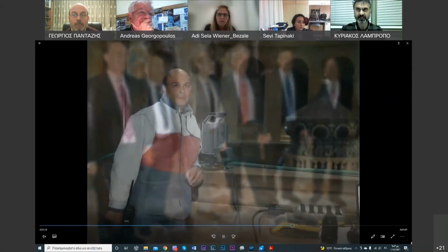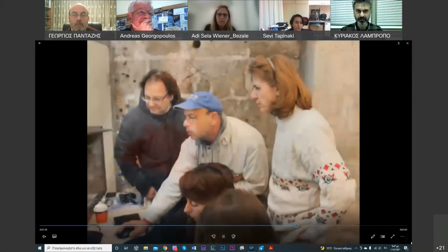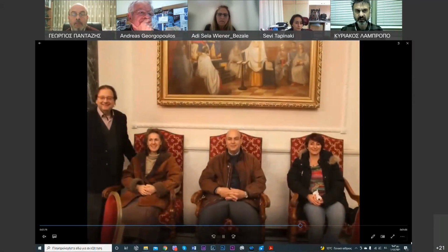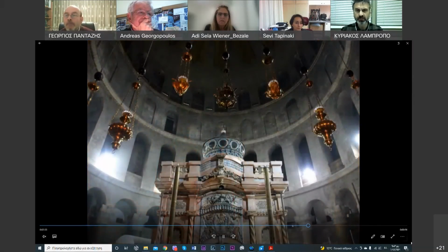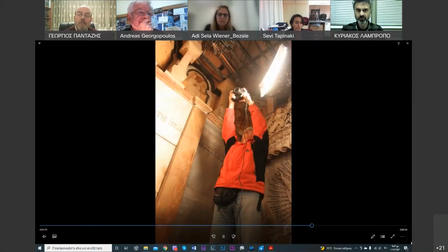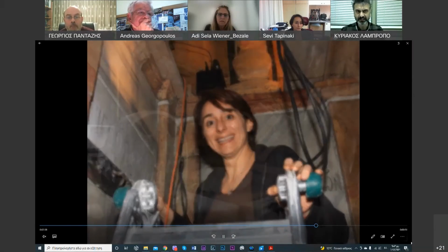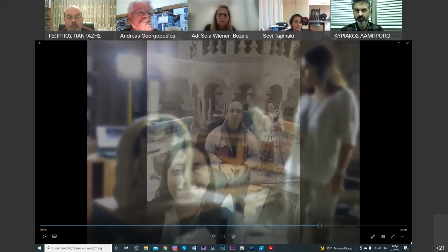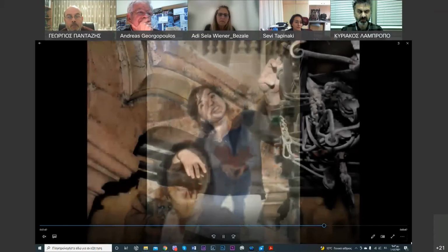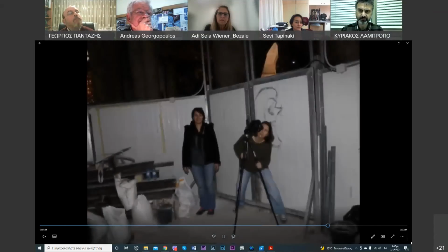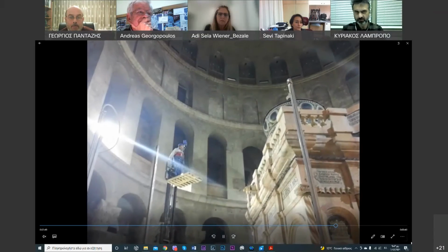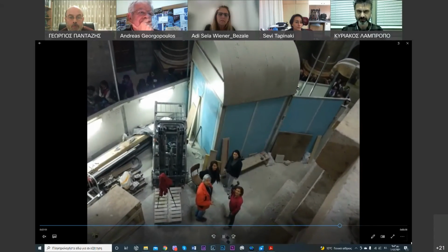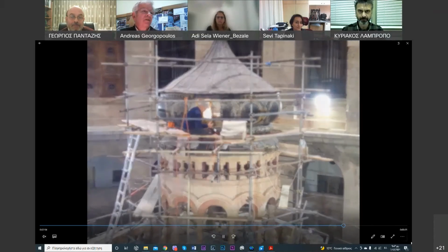The whole Edicule is actually subsiding, but it's not subsiding uniformly. So if we had the monitoring system, we could monitor how it's deforming. Actually, the foundations are differentially subsiding. That's why it would be important to have all this data and perhaps be alarmed that it may be shifting in one direction. Just to continue your comment. Sorry for. No, it's very useful.